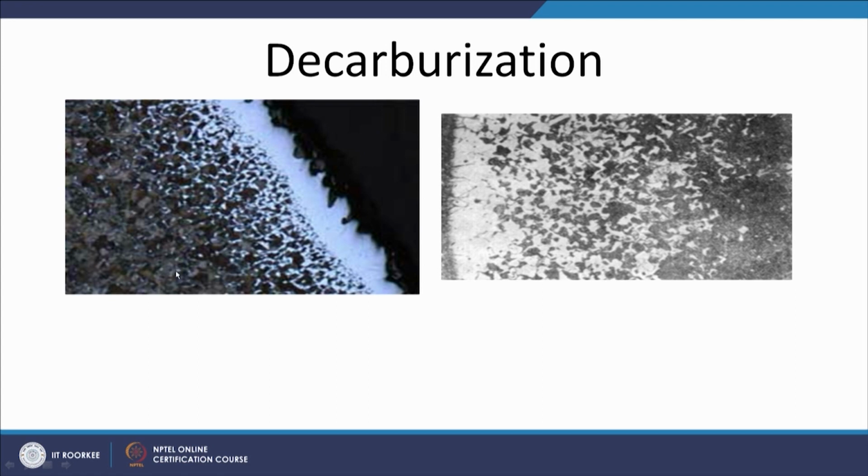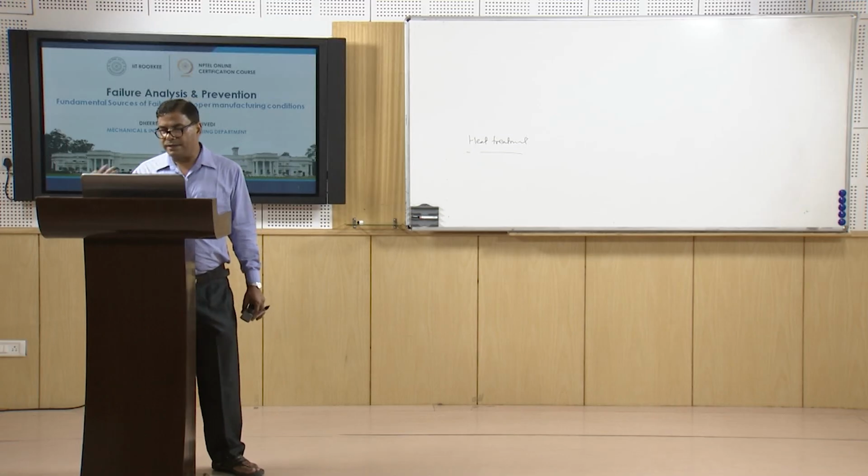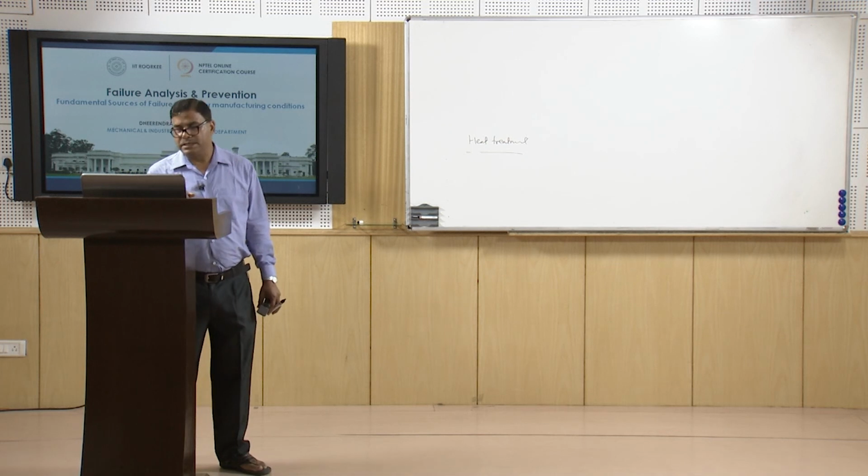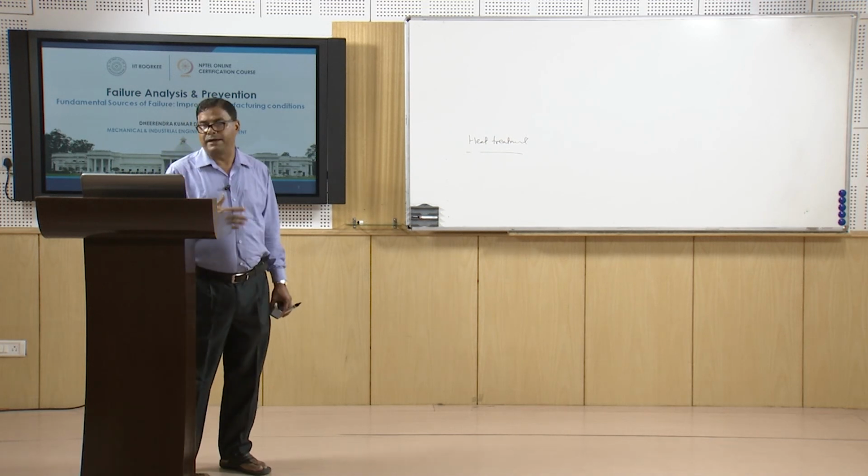Here we can see the ferrite and pearlitic structure, but the ferritic structure, which is light etched, white in color, is increasing as we approach the surface, and this can be seen in both diagrams. The increasing percentage of ferrite on approaching the surface indicates the loss of carbon, and we know that ferrite is softer, of high ductility and of lower yield strength as compared to pearlite.